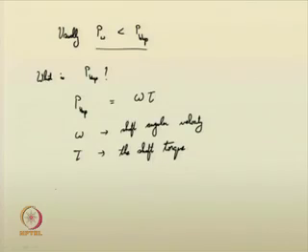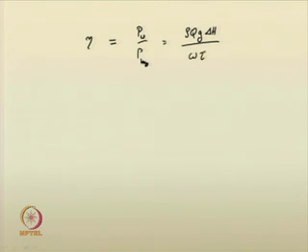Therefore, we can devise an efficiency factor. So, eta, let us consider the efficiency factor. This is nothing but equal to Pw by P bhp, where eta ranges from 0 to 1. Eta is equal to Pw by P bhp, that is rho q g del h by omega tau.